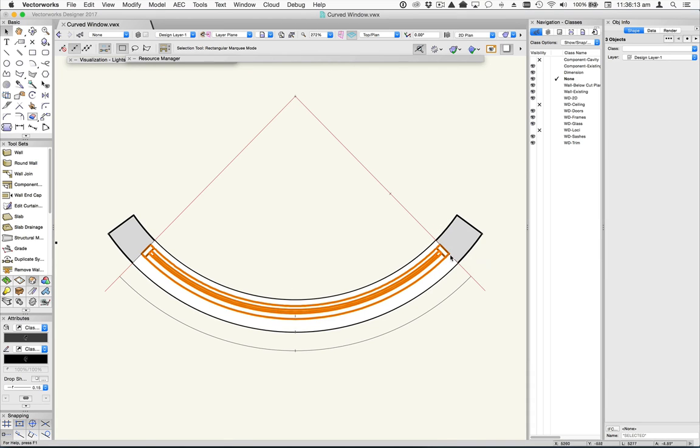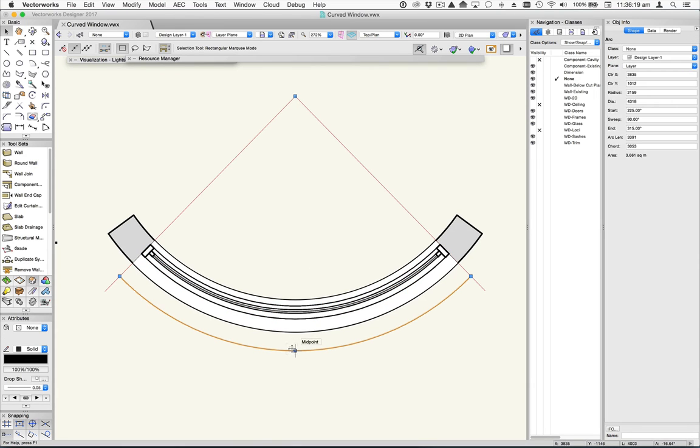Okay, so there's one final 3D thing that we have to define, and that is the shape of the wall hole. In other words, this is the hole that's going to define the cutout shape. So we'll utilize our last remaining one of these, and generally you want to make this oversized, so you're going to draw a shape that goes from 100 millimeters beyond the wall to 100 millimeters the other side of the wall. So that's going to be 270, 370, 470.